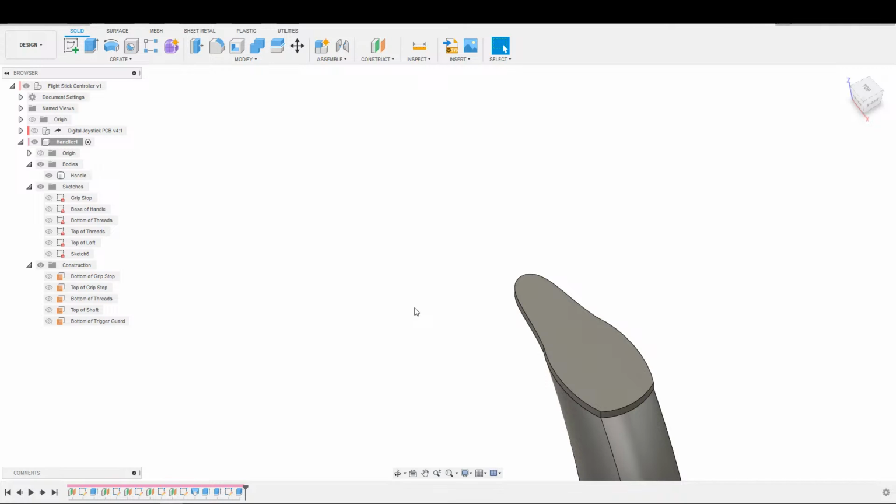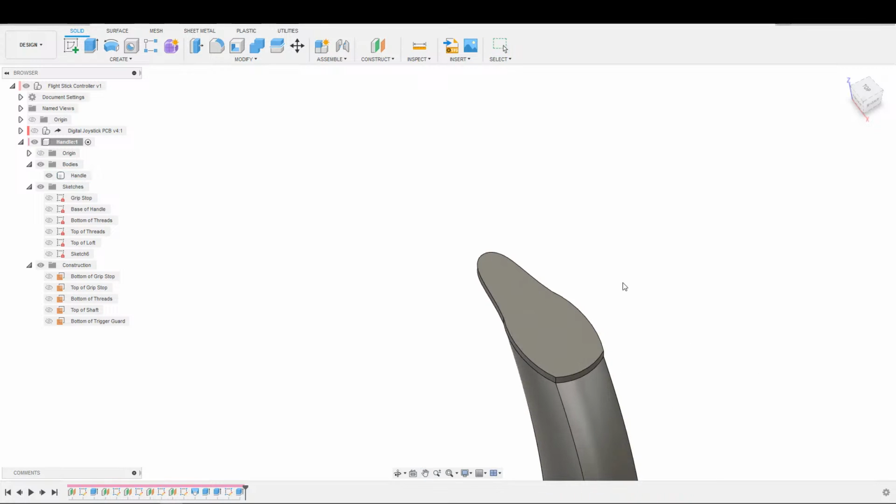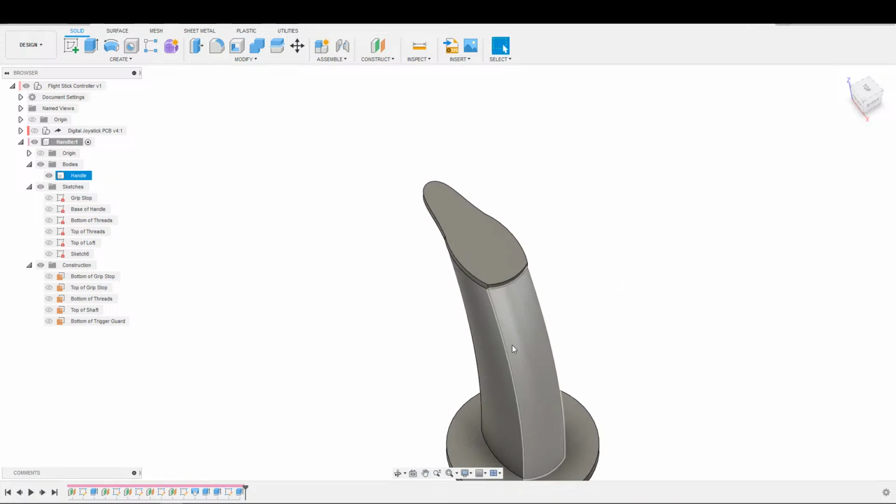When I print this, normally with clamshells, when you split this in half and shell it out, you have a ridge around the edge so that they nest into each other. If they're printing on that side, that is a little bit annoying. I was gonna say maybe I just get some filler and fill it in to cover it up.